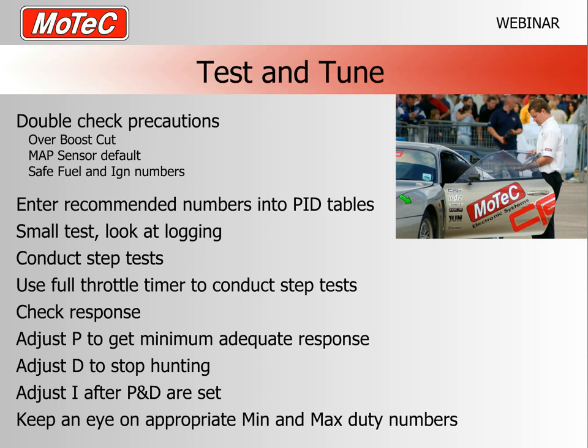Small tests. Now, absolutely, whenever I'm doing this kind of work on anything with any sort of decent sized turbo, I'm just going to open that throttle and feel the boost come on, and then look at it on the dyno, or download the logging and have a look. And you can see on that first little test if the boost is going to go crazy and way too much. And then just progressively start to test a little bit harder and longer. Just don't jump out there and go full throttle for 10 minutes or whatever and expect that it's all just going to work. I'm telling you, that's not the way for long engine life.